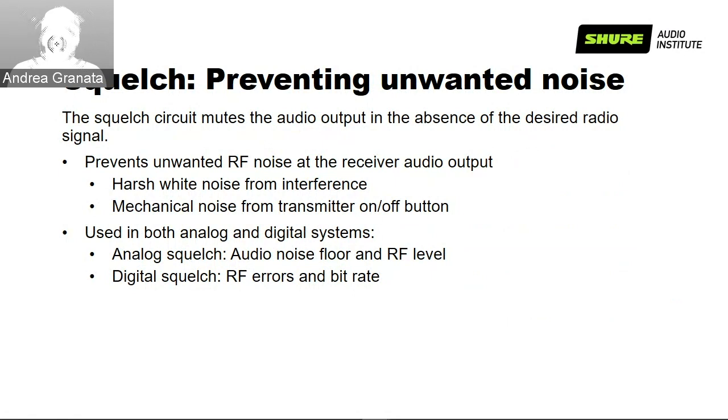But the squelch is a very important tool and feature. So let's see how it works, because yes, it's not going to change our audio output. What squelch is doing is behaving like a gate. A gate in the audio domain opens when we have enough signal.